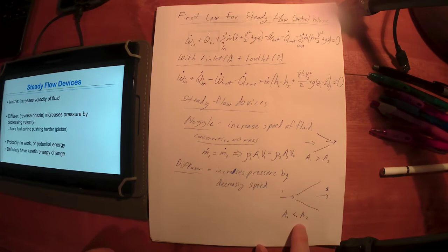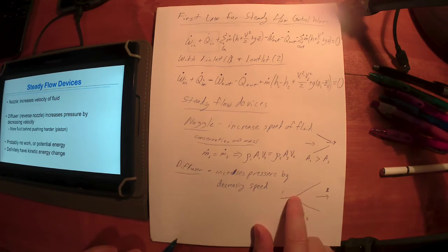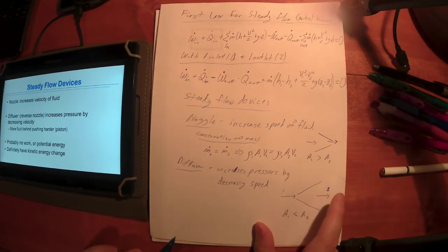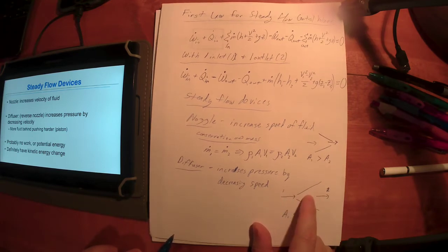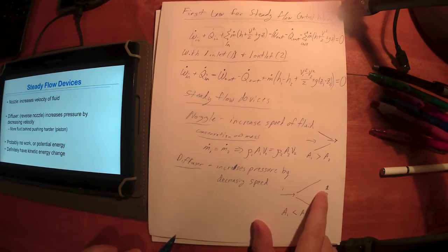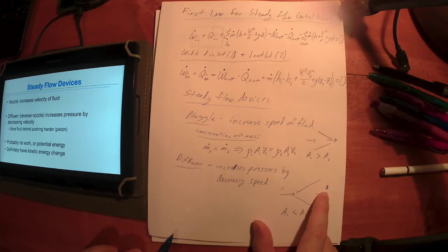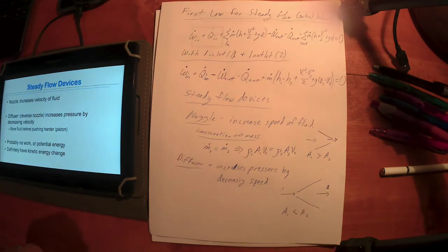And what happens is, as it does this, the fluid slows down, and more high-speed fluid's trying to get in here, and it's trying to push this low-speed fluid as it slows down coming in. This fluid tries to push it out of its way, and as it does, it's applying an increased pressure. So as the fluid slows down, that kinetic energy has to do something. Well, what happens is that kinetic energy turns into essentially pressure, which shows up then essentially in the enthalpy term. Okay?